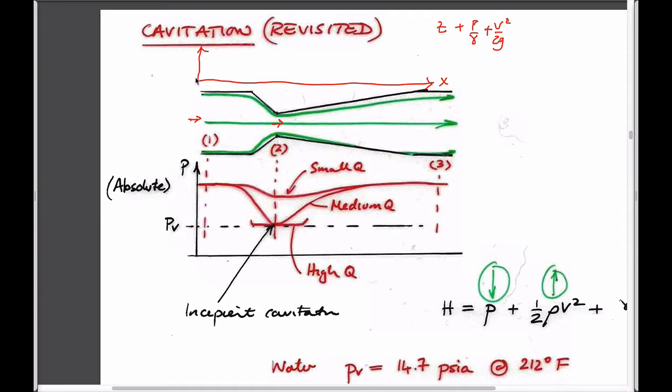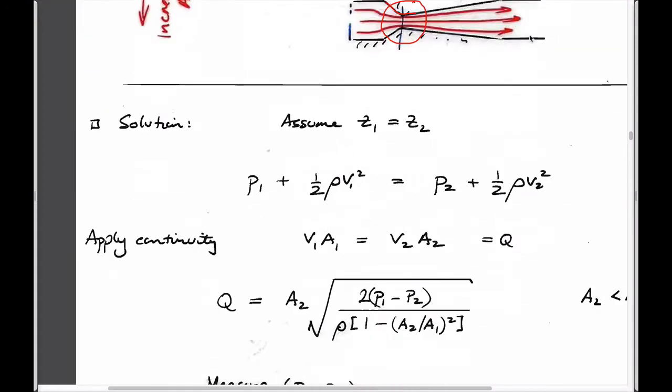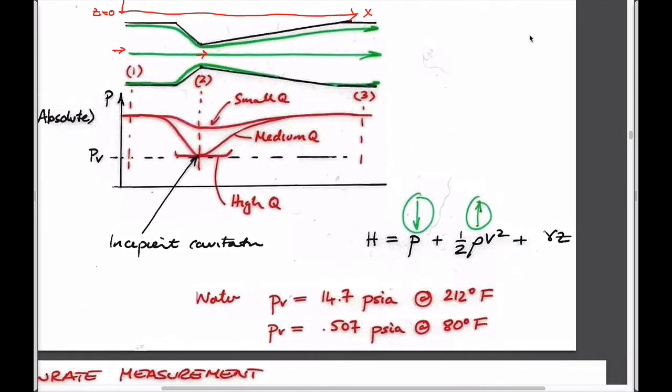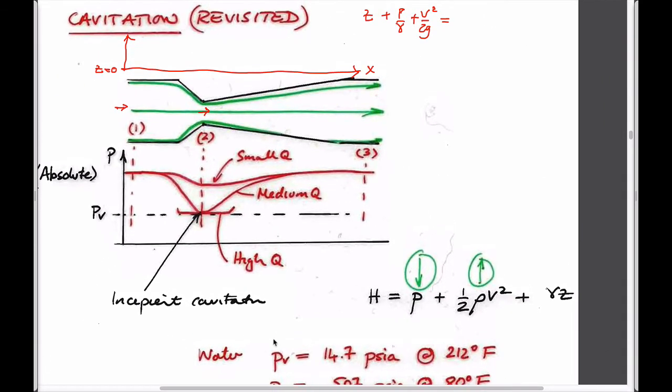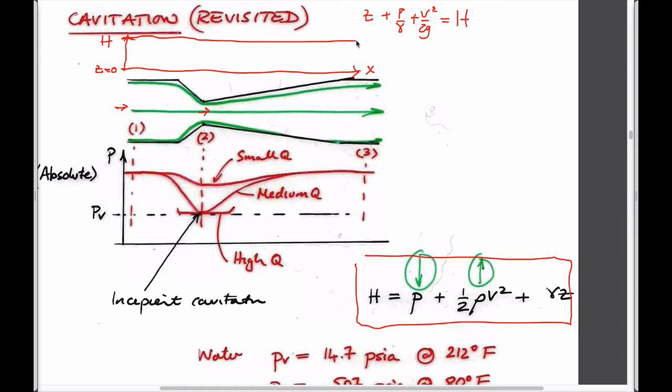So as we go along here, if we start off with elevation as 0, it's the same elevation all the way along here. What would the profile look like? We know that the sum of these, which we have called H, so I guess that's already written there. So this magnitude here has to be H, and it has to be constant all the way through. And so we know that since elevation isn't changing, then any trade-off in terms of velocity has to be between these.